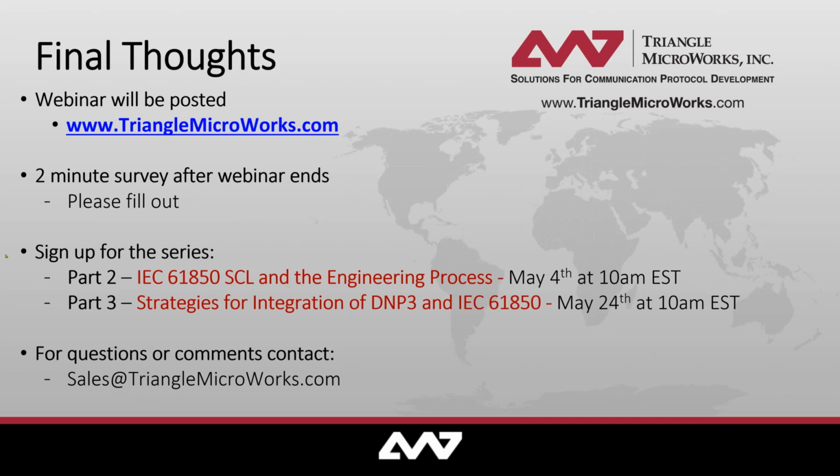As it has been answered, DNP3 supports the XML device profile, which corresponds to an ICD file in 61850. And we will talk about it in more detail in webinar 2 about the engineering process. But in DNP, we don't have an engineering process defined like in 61850, where we define system tools that can import this ICD file and use it to configure the whole system. So that's not available in DNP. But the whole engineering process we'll talk about in the next webinar.